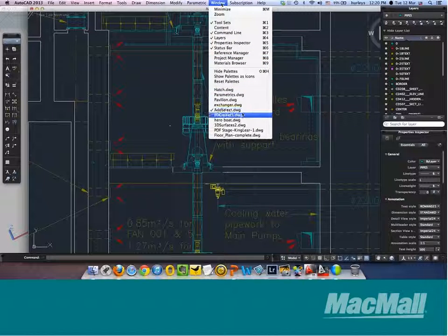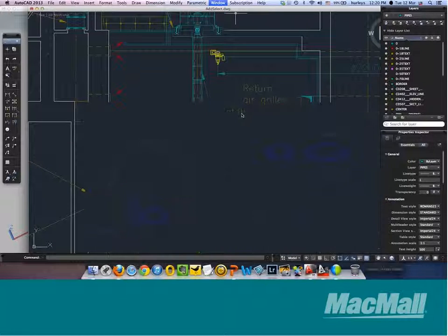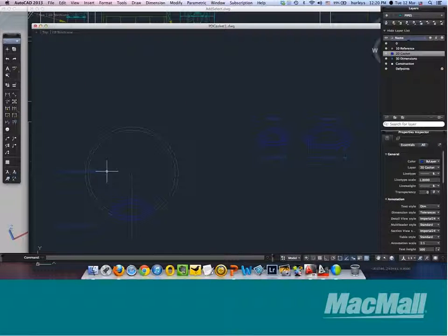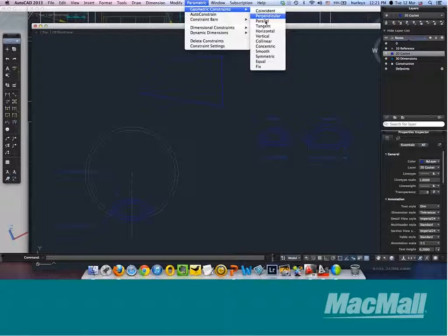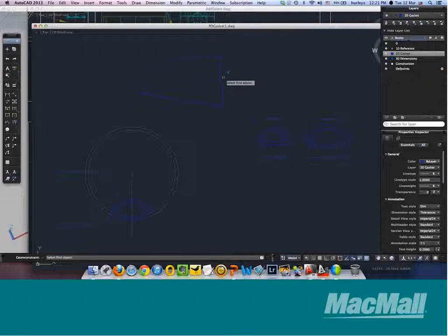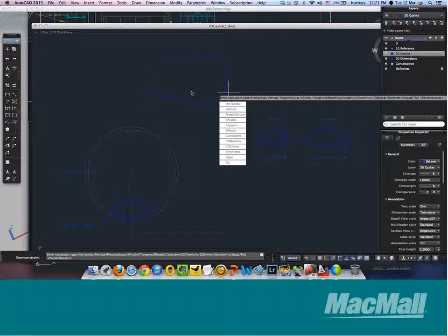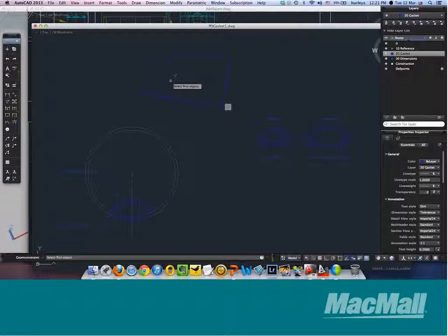Let's see here. This is nice. Before I show you this cool gasket, one thing I wanted to show you is if we just drew lines and we'll close that, we don't really have a rectangle. But if we were to go in and do geometric constraints, we could say things like, I want this line here and this line here, select it, to be perpendicular. And you see I did that. I can hit enter. I can do another perpendicular. I can take all the time I want. Then I can connect these.